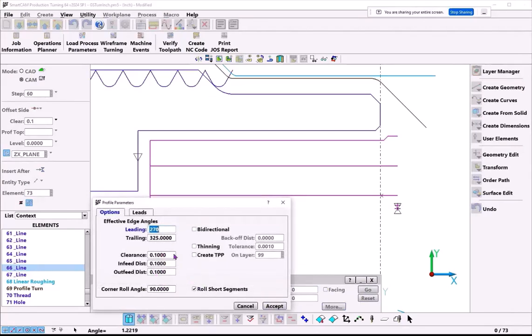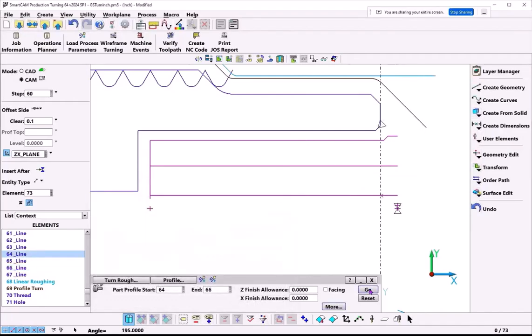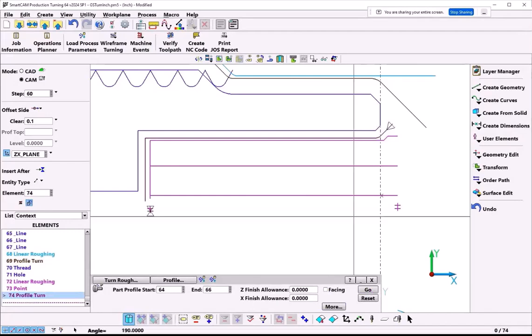And let's change, here we've got 3 different ones. So let's change them all to 0.02. Actually, the in feed probably doesn't matter, but that's okay. We'll change it to in feed is where it comes from on the outside. We'll accept that and then hit go. Very little back off. I think that'll do us.